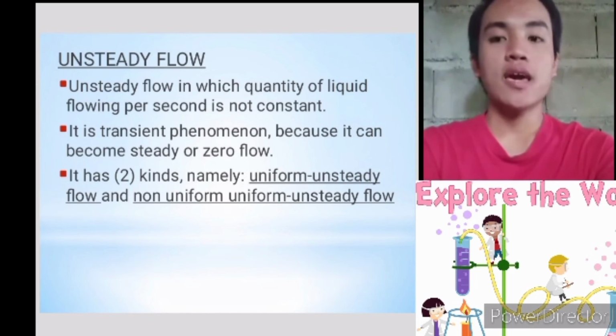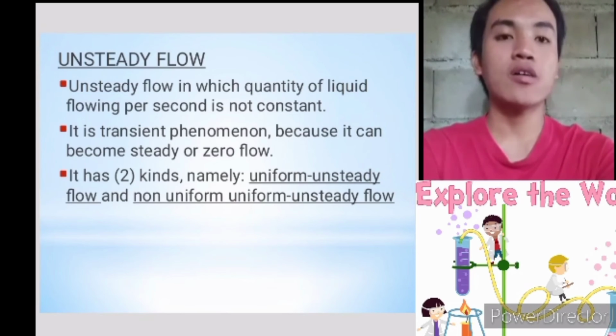Another one is it is a transient phenomenon because it can become steady or zero flow. It is transient meaning hindi siya permanent or consistent sa kanyang flowing activity or flowing processes. So the velocity of a fluid particle changes with time and position. Transient flows occur during discharge processes, during startup and shutdown processes of turbo machines, or in the case of fluid oscillations and water hammer processes.